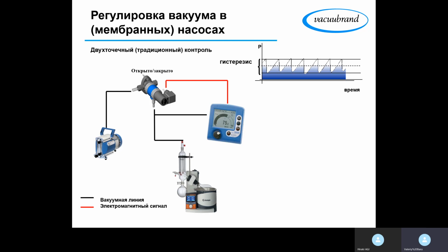The same thing for the thermostatic equipment. When we're talking about the thermostatic equipment, most customers think that if we have, let's say, a thermostat that can go down to -50, then we will be able to get down to -50. No, you won't. You will never be able to go down to -50 because most thermostats have zero cooling capacity at -50. It means that it can cool down itself, but it will never be able to cool down your application.